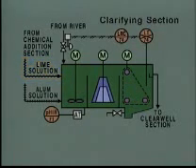If the hose is okay, we would need to check the components at the other end of the hose, in the system that makes the lime solution. It's common to have to trace flows upstream to other systems to locate the causes of problems. This often means that more than one P&ID may be needed to troubleshoot a problem. For our problem, we'll need to look at the P&ID for the chemical mixing section.